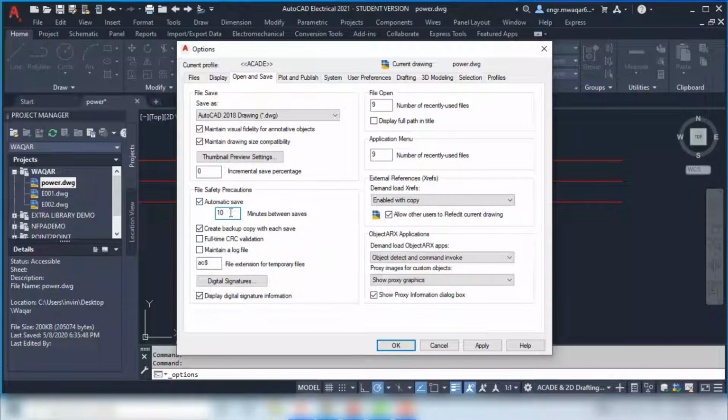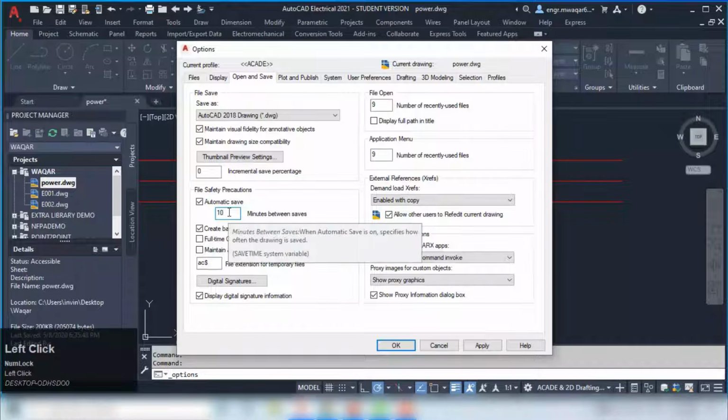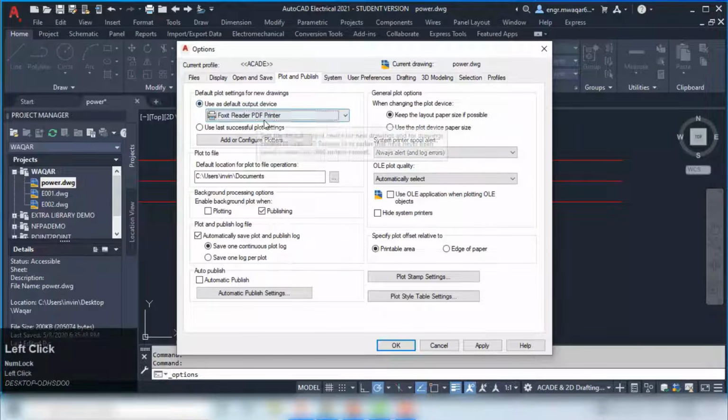And while you're there, the life-saving autosave setting lives there too. Right, the default is 10 minutes, I think. It is. But if you're working on a huge project or maybe an unstable system, you might bump that down to 5. It's a small change, but it's insurance against lost work.